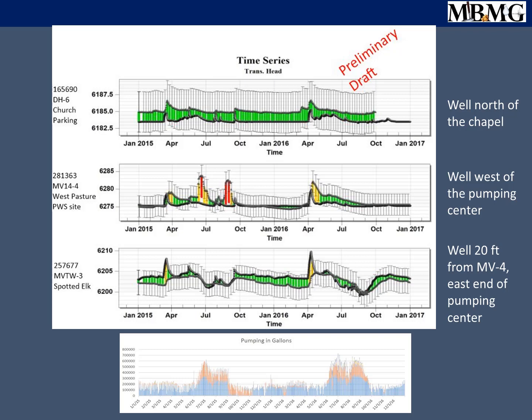Inadvertently, the Big Sky or Gallatin River Task Force gauge on the West Fork has this little arm that hangs out over the stream and measures stream stage, but it also created a great record of snow accumulation and melt. Using the weather station data and that snow accumulation and melt, we could quantify how much water piled up in the winter and then melted. I took about 80% of that and used it as recharge, and that's how we got the model to replicate the snowmelt events.